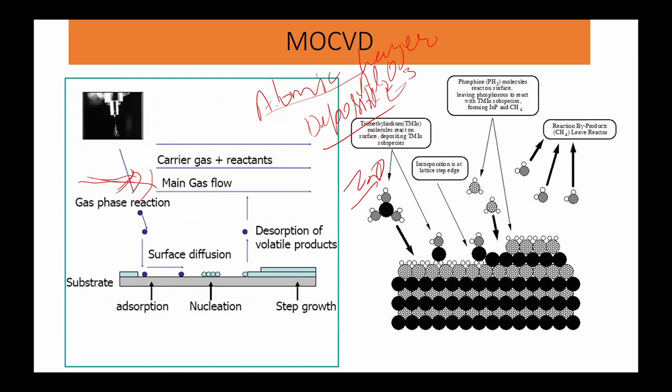If trimethyl indium is precursor 1, precursor 2 is the oxidant, which can be ozone or water. It oxidizes the trimethyl indium at the surface to make indium oxide, In2O3. Indium oxide can be grown using atomic layer deposition.